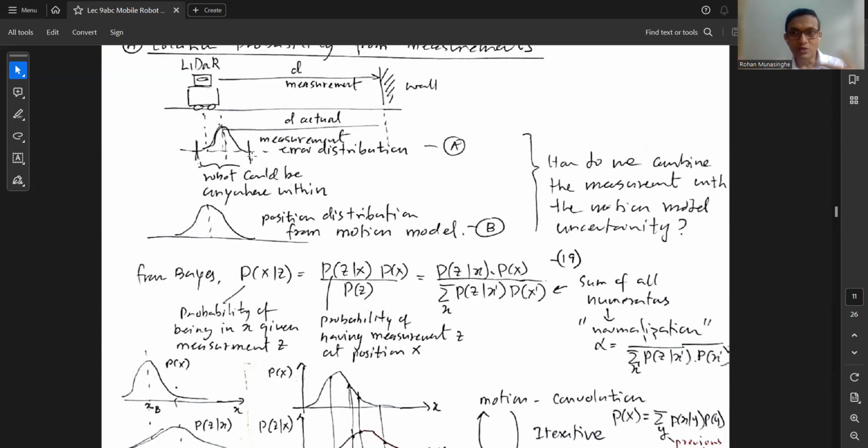But most of these sensors are more sophisticated than wheel encoders. The wheel encoders, even though the encoder itself is very sophisticated, you are connecting it to a wheel that you make. And if it's a rubber wheel, you inflate it, or sometimes you don't inflate it so much, so your diameter changes. Therefore, the circumference of the wheel is not very certain, and also the width between the wheels is not very precise, and you have some measurement that also is an error. So therefore, your vehicle model has higher errors than your LiDAR sensor. So the LiDAR sensor has errors, but not that much, generally speaking.